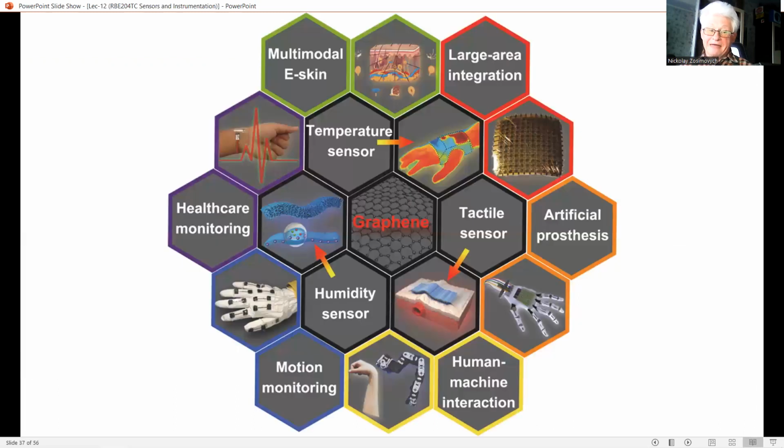Piezoelectric ceramics and polymers are also applied in the acoustic domain. Application examples, including tactile sensors, will be discussed in the next lecture part on acoustic sensors. The integration of polymer technology and silicon technology offers interesting prospects for future developments of compact, high-resolution tactile sensors with integrated electronics.